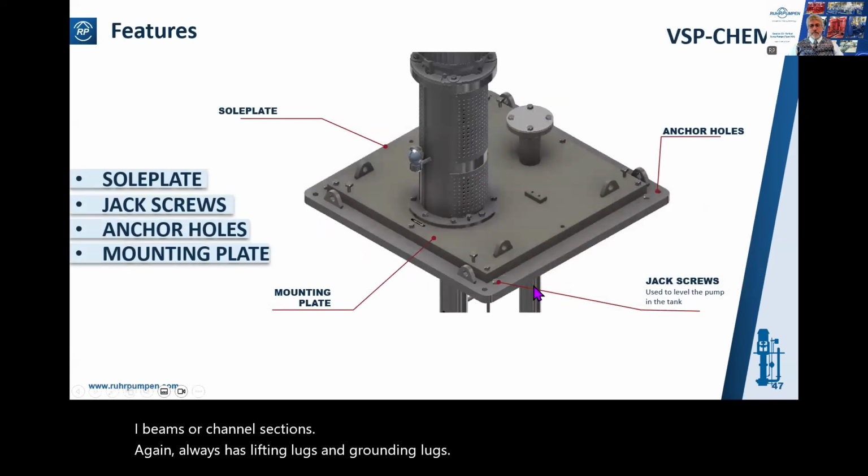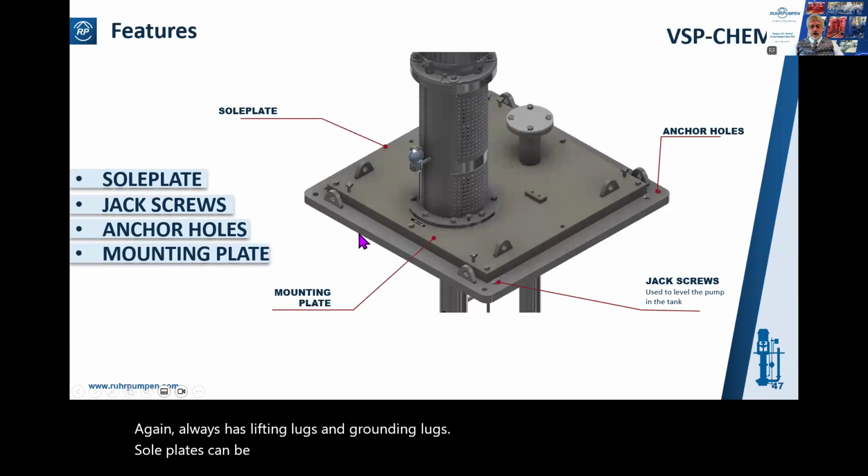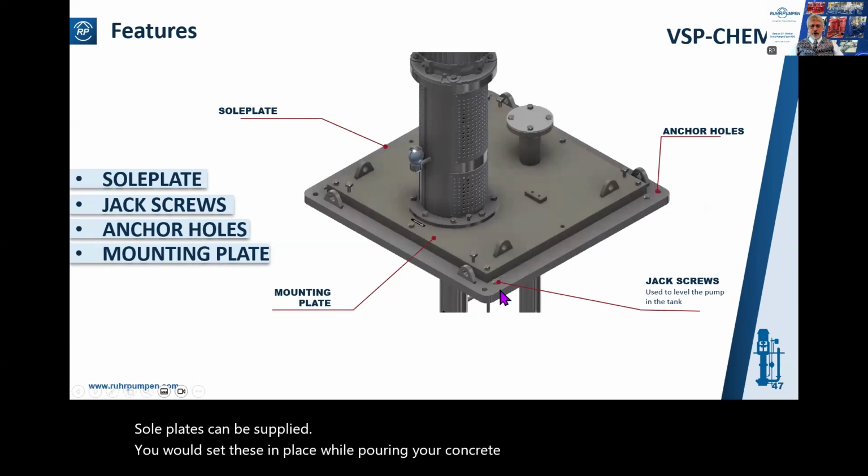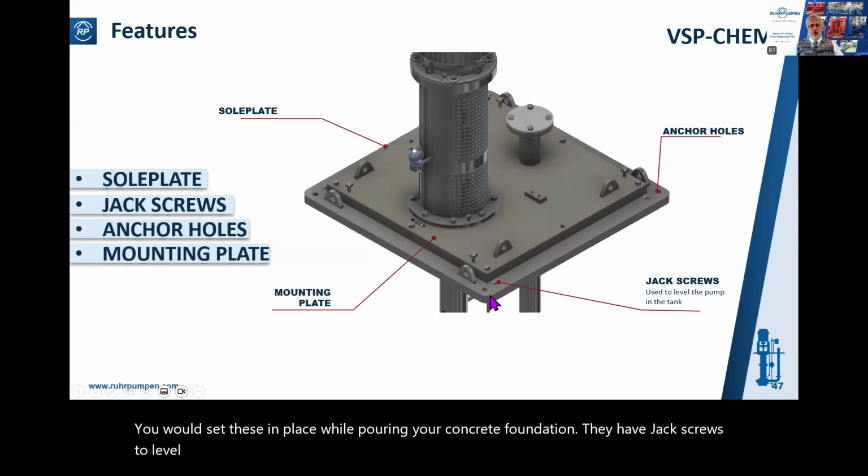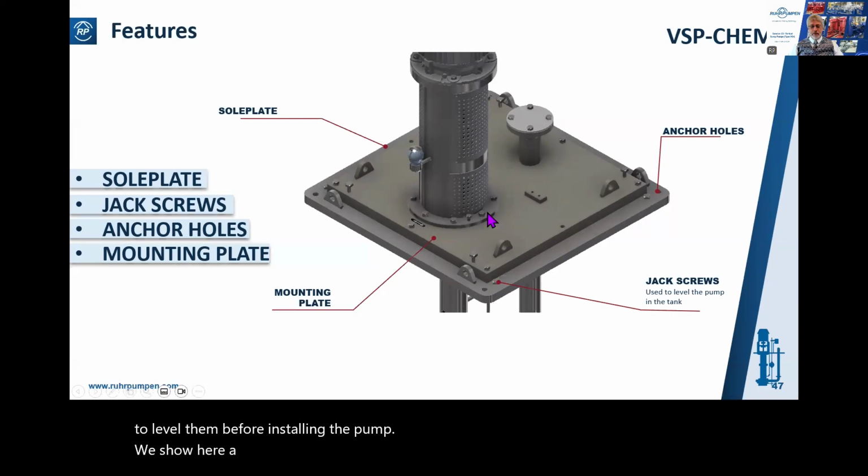Sole plates can be supplied. You would set these in place while pouring your concrete foundation. They have jack screws to level them before installing the pump. We show here a square pump head plate. It could equally well be a circular plate.